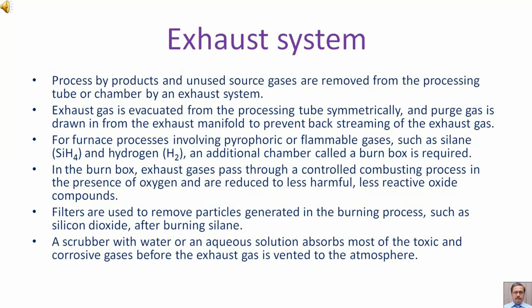Filters are used to remove particles generated in the burning processes, such as silicon dioxide after burning silane. A scrubber with water or an aqueous solution absorbs most of the toxic and corrosive gases before the exhaust gas is vented to the atmosphere.